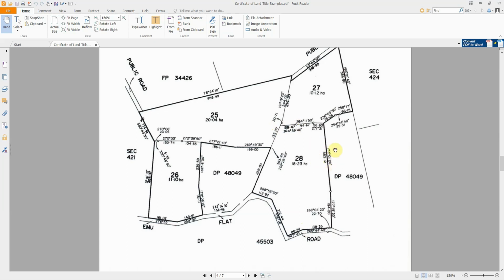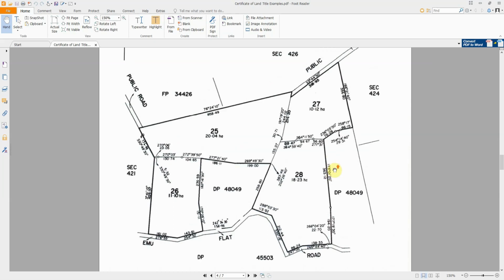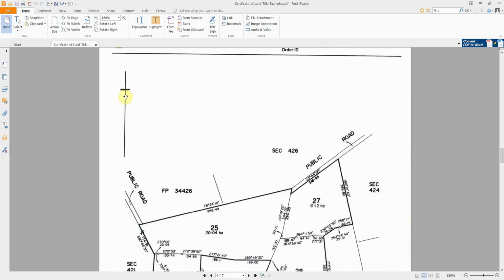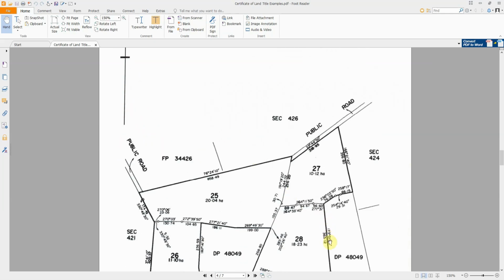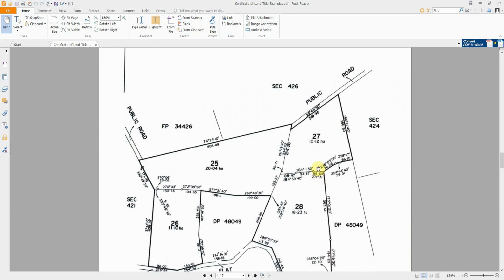Okay, so the point we can take from here: this boundary is made of different segments. When I say segments, we usually refer to straight lines. Simple as that. Each one of these segments has two components, length and bearing angle. The bearing angle describes, if I take from north an angle of 173 degrees, 1 minute and 20 seconds, I'll be drawing that line accurately, and the length of that line I should be drawing, 363 meters and 12 centimeters, for example.